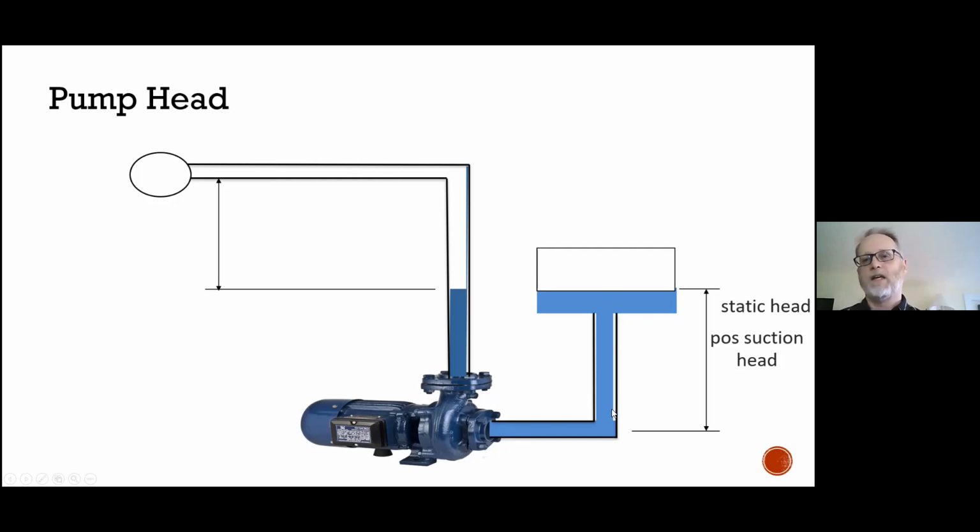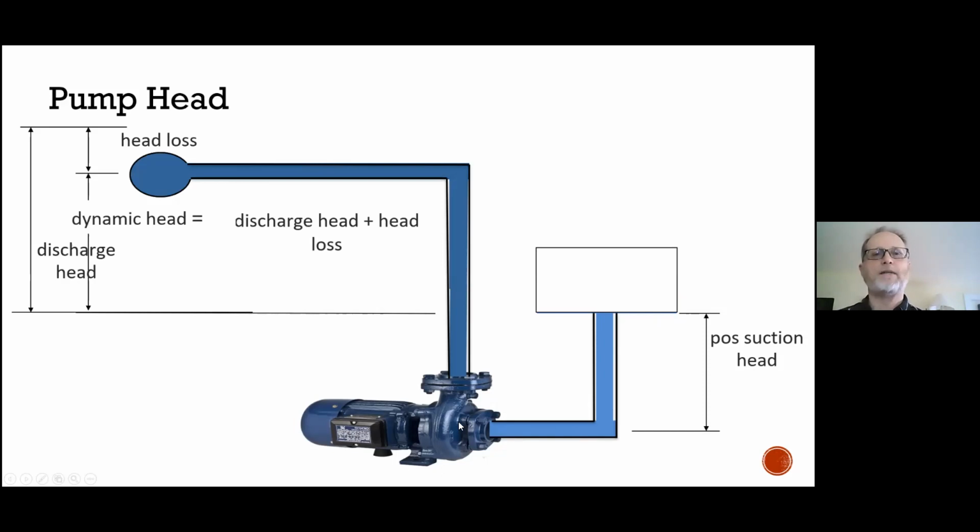And this is on the suction side of the pump. The pump turns on. This is where we have to discharge it to. So we have an elevation called the discharge head, which is this line here to the center line of our reservoir. But we lose energy through friction based on the diameter and the size and age and configuration of this pipe.